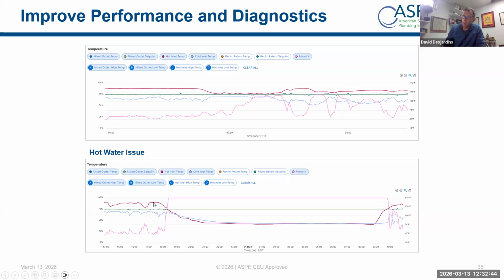You can see it. You see the hot water line, and that just drops, and then the mixing valve just opens wide open. So I just said, hey, look, it's not a mixing valve problem. You got a boiler problem there. So that was one of those things that was really useful. My gosh, 2 hours away from the project, and we started talking about it, and then he knew what to go do or look at when he got there, right?